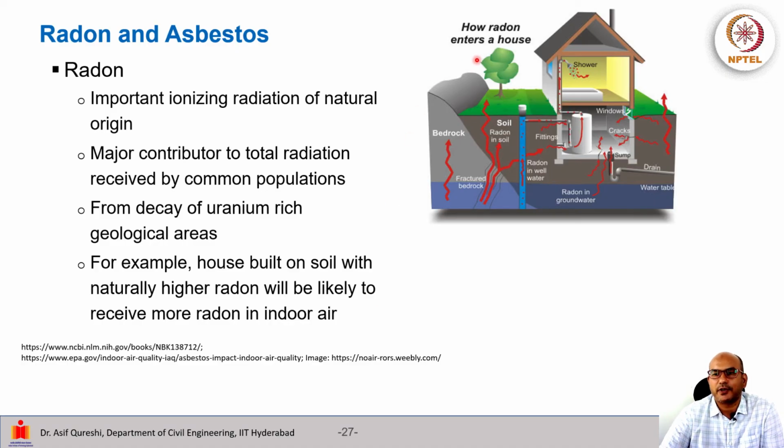So here we have how radon can enter a house. In this case, it is seeping through the soil to the air and then traveling from outside to inside through windows. It can travel from soil cracks through building cracks to indoors. If it's in groundwater, through pumps, it can come into the water area. Same through fractured bedrock and borewells, it can come to the indoor water collection system, and once it comes there, through shower or drinking water or any kind of water use, it comes inside. Here it's just coming up and occupying the outdoor environment, and then through a window here it can come inside.